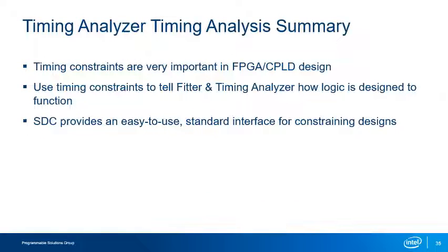This concludes the Timing Analyzer training. So, to sum things up, timing constraints are very important in any FPGA or CPLD design. To guarantee that your design will meet all timing requirements, you must constrain all paths in the design, but at least the clock and I/O paths. The Timing Analyzer provides an easy-to-use interface for creating SDC constraints and verifying timing with its extensive reporting capabilities.